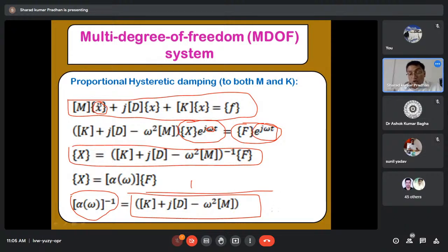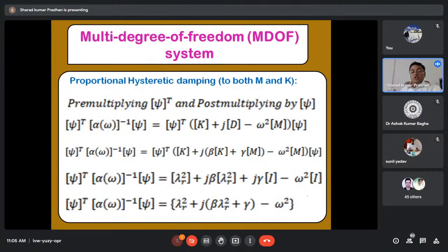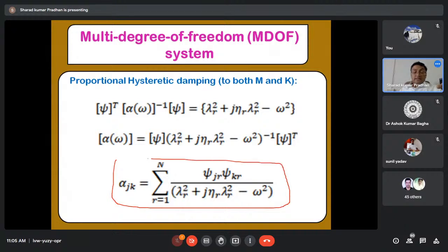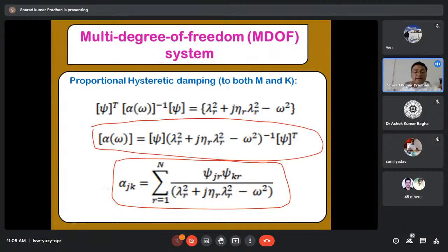And directly this formula is going to give you dynamic stiffness. If you want to convert K, D, M into omega, zeta, or in this case eta and phi, you can do those manipulations, pre-multiplying, post-multiplying, n number of mathematical manipulations here and there, and you are going to get this formula, which is the single FRF. This is the full FRF and this is the single FRF.